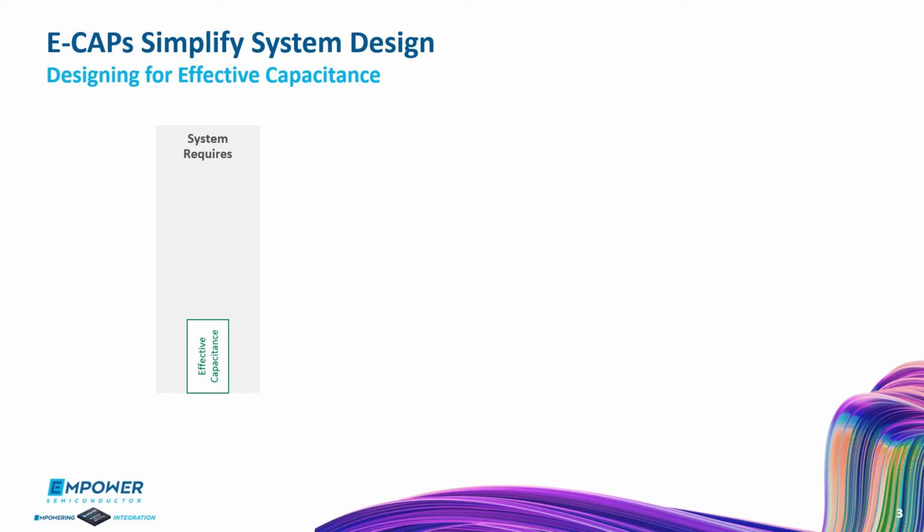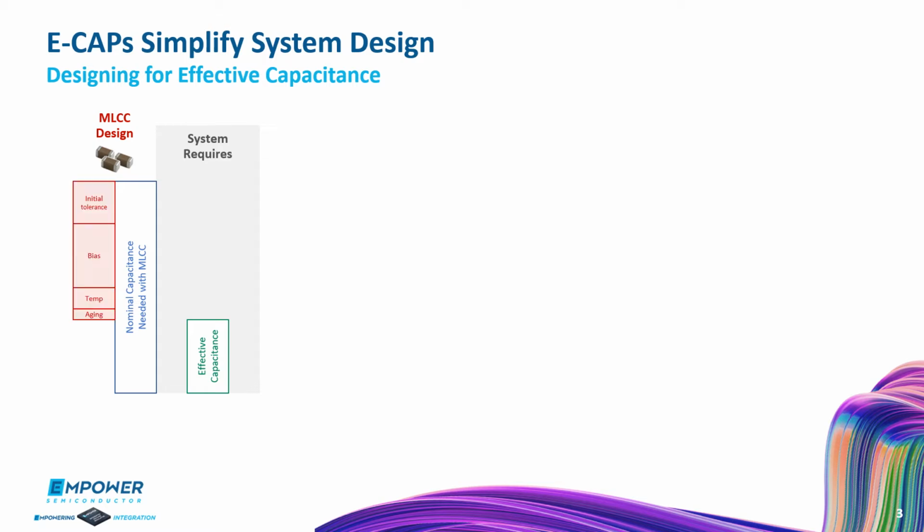For a system that requires a certain amount of effective capacitance, if one chooses MLCCs, they should design for a much higher nominal value to account for tolerance and degradation due to voltage bias, temperature, and aging. This often requires multiple MLCC parts and the overall ESL is large, in hundreds of picohenry range.